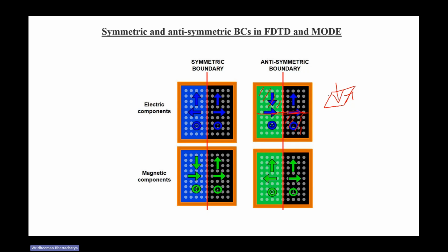So by this, the simulation regime, suppose this is a nanopillar symmetry, the simulation time and space get reduced by a quarter, right? It gets reduced by a quarter. So if only this part is simulated, it can stitch up the remaining part. So these things can only be used when we are doing nanohole arrays, or any nanopillars, plasmonic nanostructures or metasurface nanostructures, based on their application.